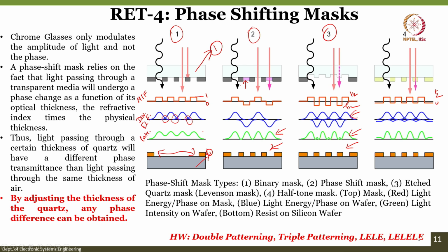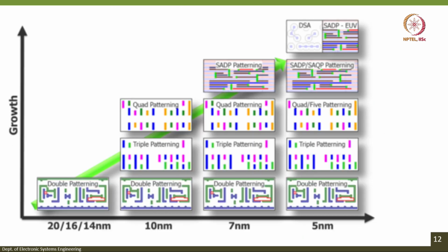Now, we can further go and get as small as possible, right? Sounds very good, but when you are using lithography and etching multiple times, it comes with its own cost and complexity. Hence, people limit it and prefer to do it in one exposure if that is affordable and better, and that is where all the magic I have quickly discussed comes into the picture: phase shifting mask, off-axis illumination, optical proximity correction, or immersion lithography.